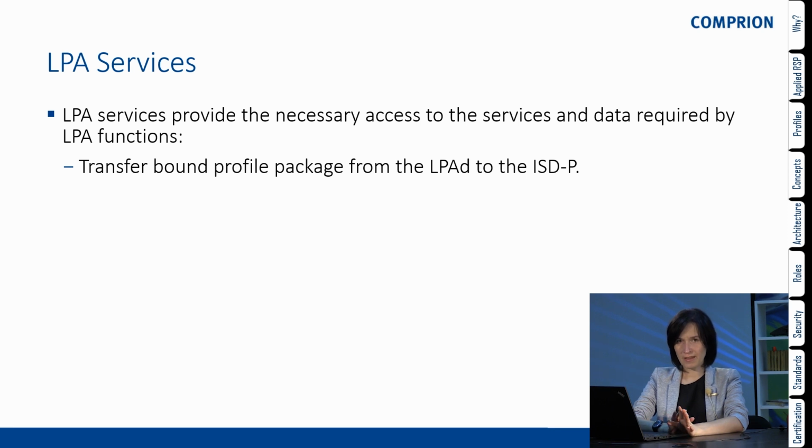Okay, here again, inside of the EUICC, we have this architecture with the different security domains. Inside of the EUICC in the consumer world, we have a similar structure as in the M2M world. We have the security domain, the ECASD, the EUICC controlling authority security domain, which is responsible for the cryptographic operations. Then we have the ISD-R, the issuer security domain.